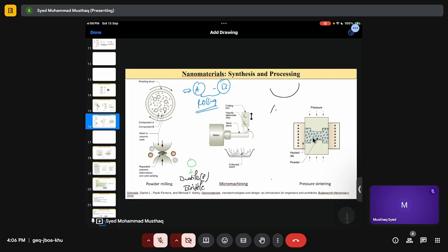say this is okay. If I have a brittle particle, it will break. Right, there is this breaking. And if you have a ductile particle, it will just simply deform. It will not break, it will deform, just like here. See? It is just getting deformed, it is not breaking. So it will take lots of time to do the milling.